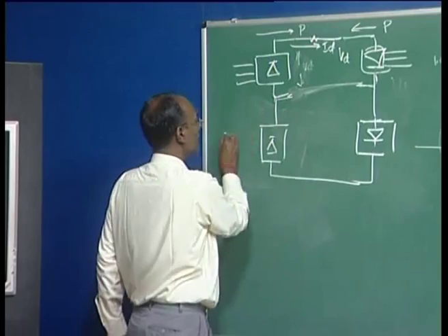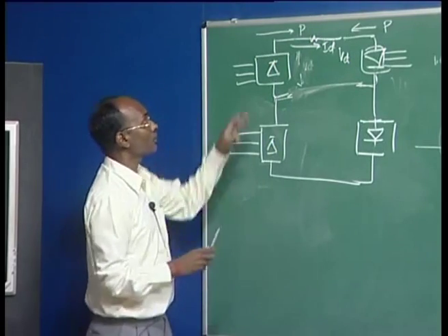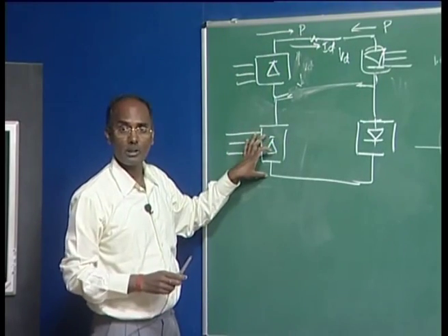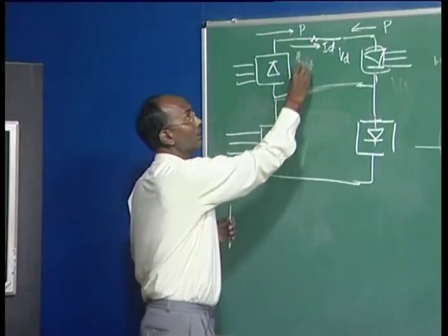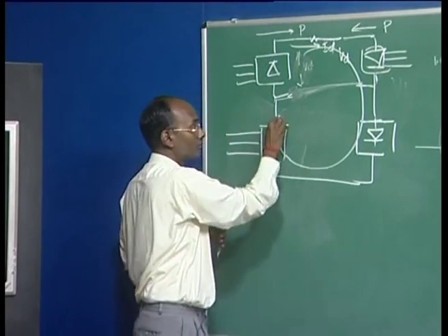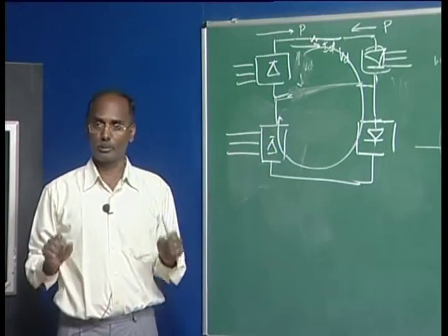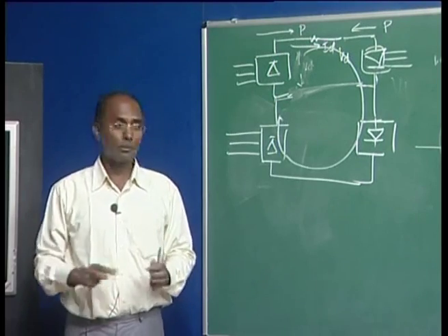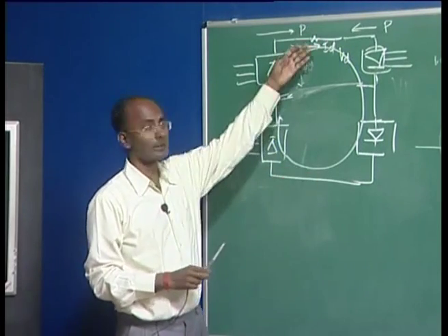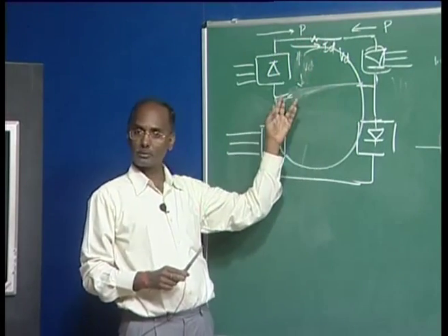This is your grounded three phase. Now this is one pole, this is another pole. As you know, the current here is flowing the same current if it is bipolar. In the monopolar, this current may be different, this current may be different, and this total is flowing through the ground.